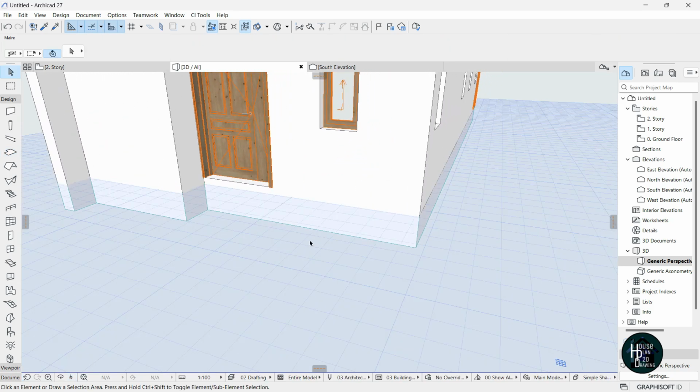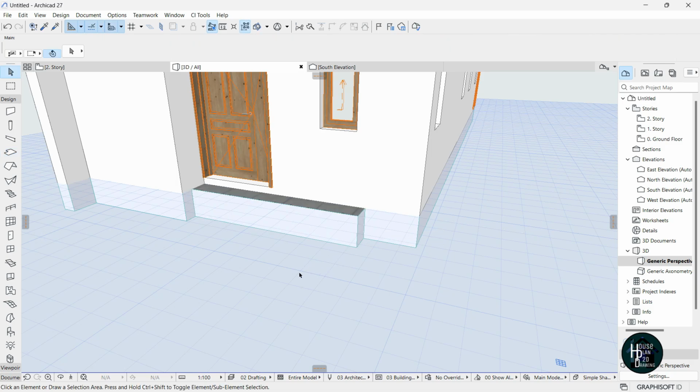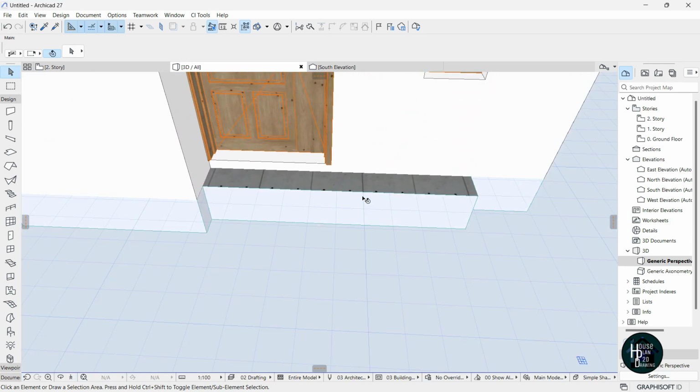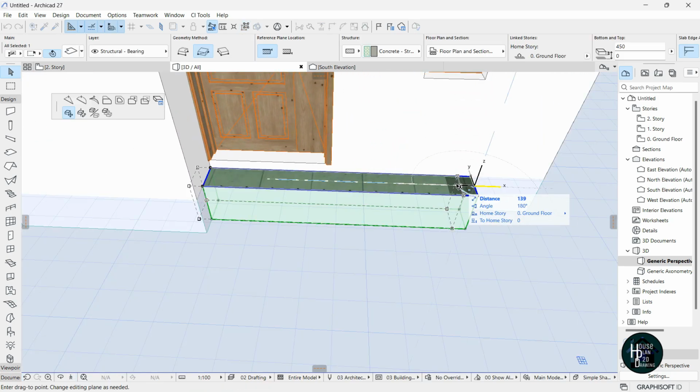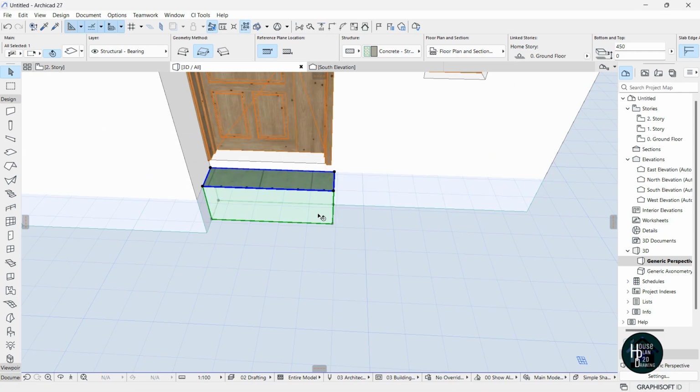For us to go about that, I want you to hold on Alt, select this slab. Once you select the slab, click this, stretch it outside like this. Now I want you to click Tab on your keyboard to select the second dimension. Click Tab twice, 1, 2, and give a distance of 300. Click Enter. Once you do that, move around here. Click this slab again, click this edge here, make sure you're selecting this offset edge and just move it closer to the side here, like so.